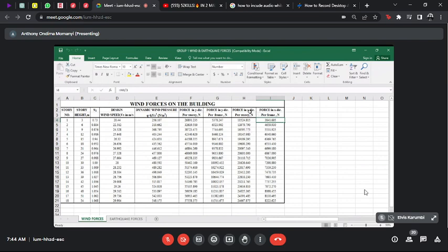Column H was the force in the x direction per story. We divided by 3 because the number of full frames in that direction were 2 plus the 2 outer frames. So those are the forces in the x direction per frame up to story 18.